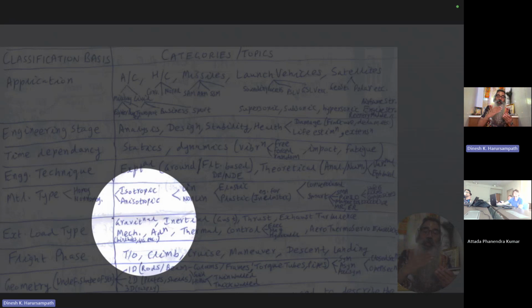Nonetheless, you will have certain transfer of loads from the ground through the tires to the rest of the landing gear system, and then therefore to the aircraft. The way the landing gear is attached to the aircraft, it could be tricycle or whatever kind of landing gear configuration you have. So those are very important structural loads that we need to deal with, and that is one exceptional place where, as I think very briefly mentioned earlier, steel continues to be used.